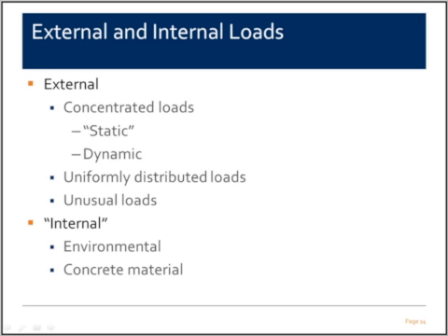And it could be uniformly distributed loads, such as, if you had an above ground water tank or wastewater treatment tank, you could have uniformly distributed loads. Or it could be unusual loads due to construction, random loading, soil swelling, loss of supports. All these things are possible.